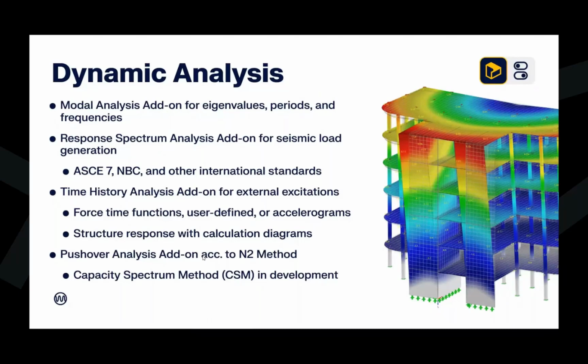If we are interested in carrying out a seismic load generation, we would want to utilize the response spectrum analysis add-on. Within this add-on for seismic loads, we do have the codes implemented here, the ASCE 7 and the NBC standard. And with the response spectrum analysis, this is applicable to any structure type.